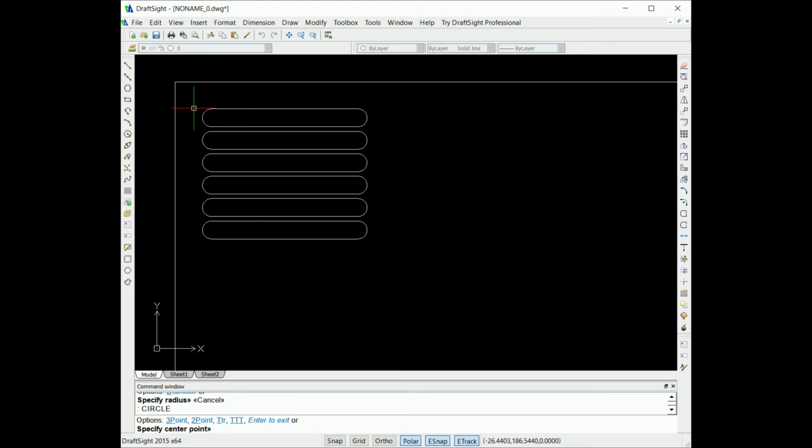And as I always say, look down here at what I'm doing. So I'm going to use the at, which is relative positioning. And where I want that hole is at, and I'm just guessing here, minus 0.75. Let's just say that's where our hole X position is. And it'd be minus because we're going to the left with this hole.